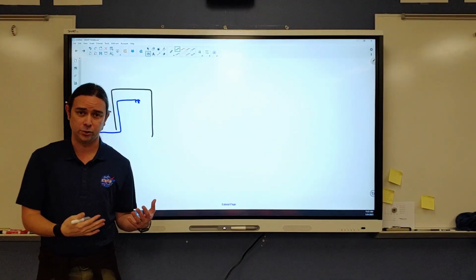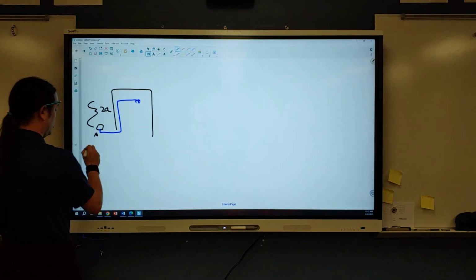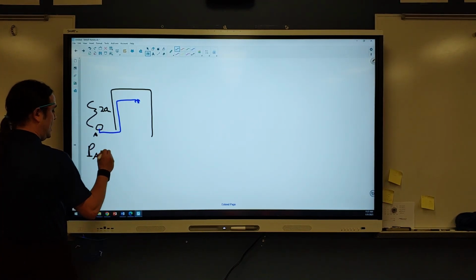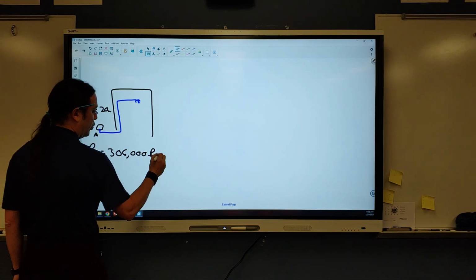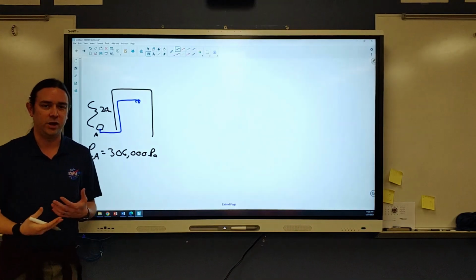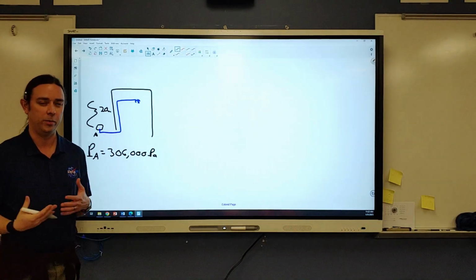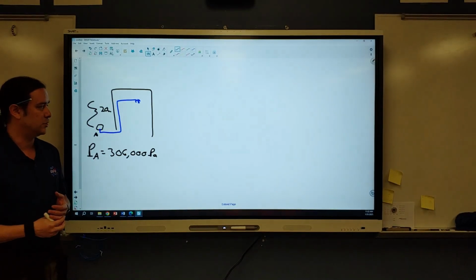In order for us to actually try and triple the speed of the water, we could derive the solution, although that becomes problematic because I've been given that the pressure supplied at point A is 306,000 pascals, or 306 kilopascals, as the case may be. You can do a derivation on that, but you're going to end up with a whole bunch of terms, so this is one that might be better solved with numbers, and it's the numbers that I've actually given.